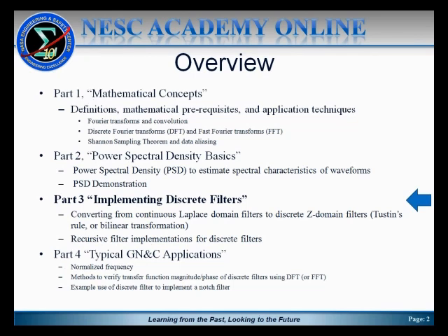We also will discuss how continuous and discrete filters can be implemented, such as in a simulation environment where you're trying to implement either continuous filters or discrete domain filters. We'll also show how the discrete filter form leads to a recursive equation that can be used to implement the filter based on current and previous states of the filter itself.